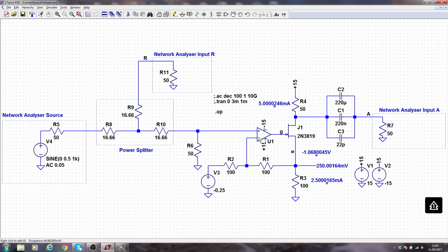So if you were in EE118, you know that its op-amp is doing everything it can to push the two inputs together. So if I was to get a data label, I would just copy this one. F6 for copy. I missed. 819.3262 nanovolts. Not very much. E minus 9, so that's less than 1 microvolt. So basically it's ground, more or less. Virtual Earth, anyway.